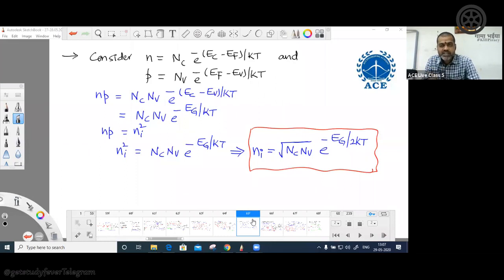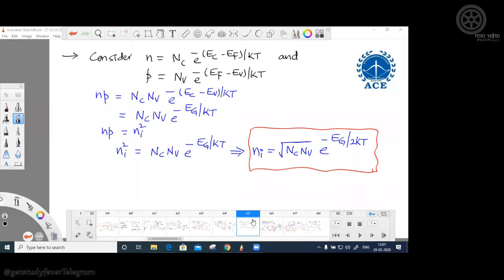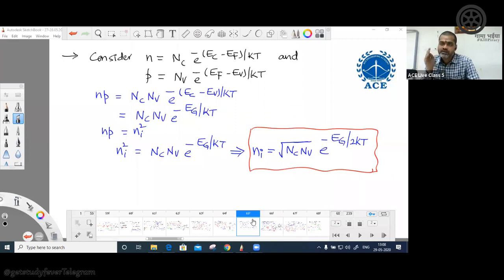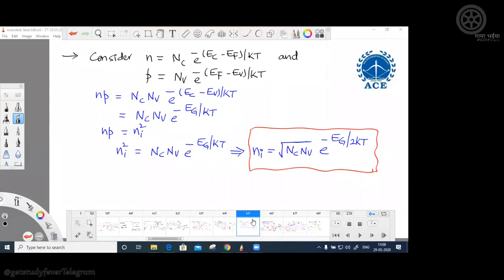But if you see the equations that we have given for the Fermi energy level, you can very clearly see NC, NV are involved, no? What is NC, NV? Density of states. Yeah, that you must understand. Anyhow, they will mention the value, but even if they have not mentioned it, you must be in a position to understand what exactly it is. Okay, sir. Thank you.